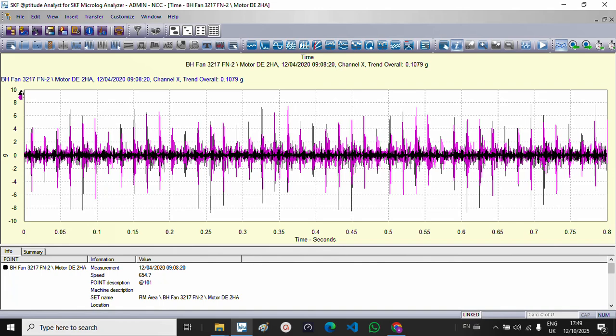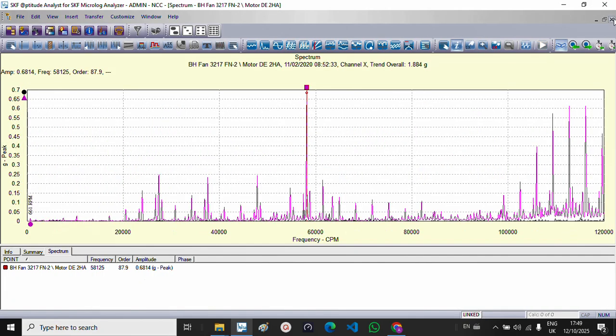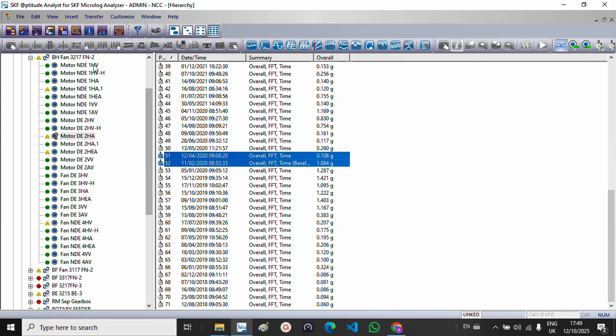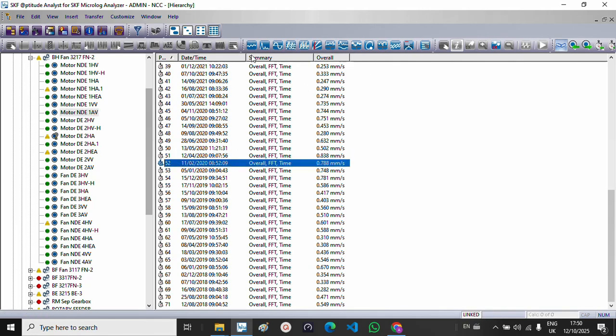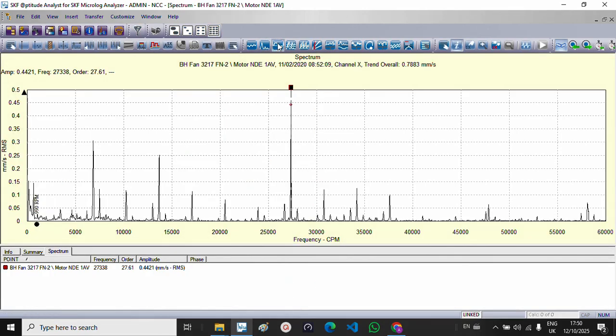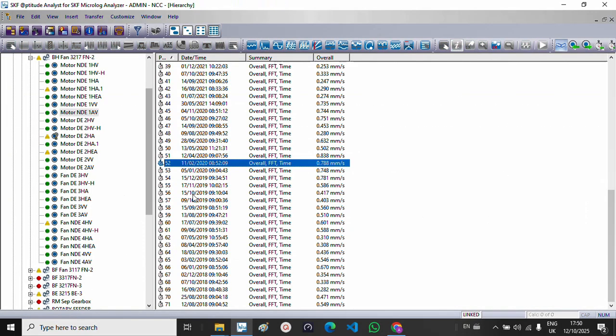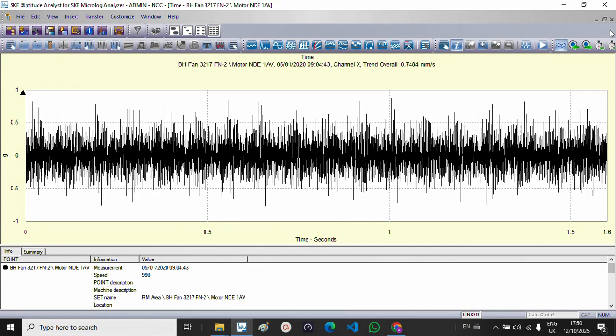Therefore, to execute all these steps for all the points in the plant and all equipment, where for every bearing we have 6 points, 4 in the horizontal and 1 in the vertical and the other in the axial, all these points need some time to analyze. Sometimes we cannot see the fault in other points or other axes, therefore we must check all axes.